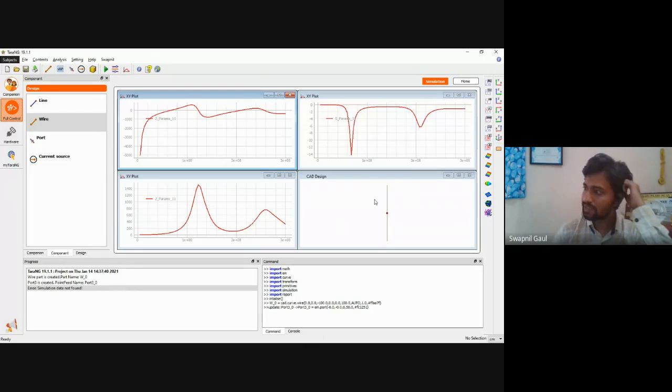So that means this open wire dipole antenna, when we consider open wire, will act like a capacitor, because there is one wire, and there is electric field coupling between these two wires. So basically, it is a capacitor. And at DC frequency, this capacitance will have zero value. That means the reactance is like minus infinity.